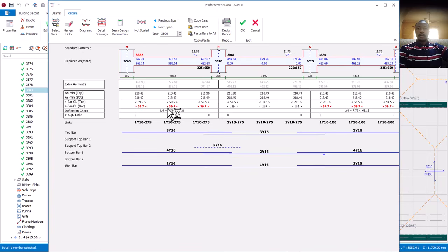It is when this place is less than 20, and your number of reinforcement here is much, and despite that you have adjusted it, there are still some failure. Then that is when you cannot ignore that warning, and you go ahead and increase your width so that it will be able to accommodate the number of reinforcement you are having here. So are we together now?